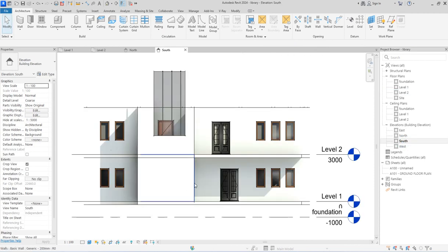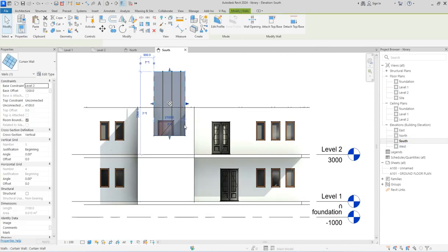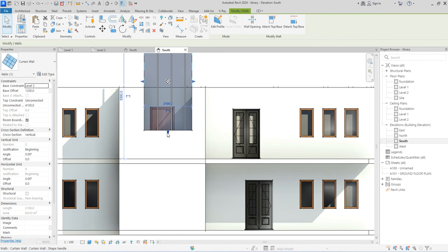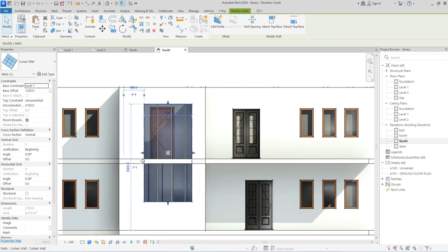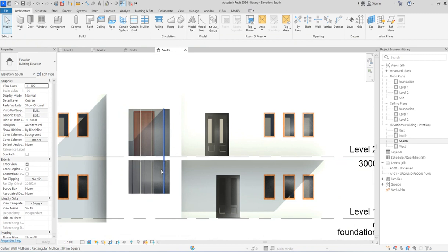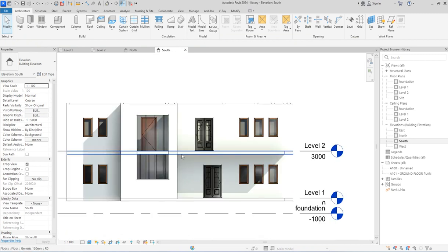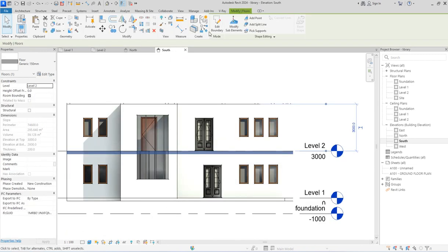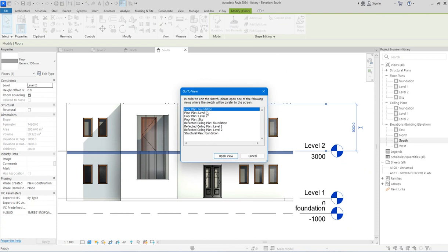It's going to give a loading pattern as well. So you select this and then you bring it down. All you just need to do is to say level 1. So everything is shifted down according to the way it's supposed to. So this is coming down as well. So select this one and say edit the boundary. So go to the boundary, say open from level 2.